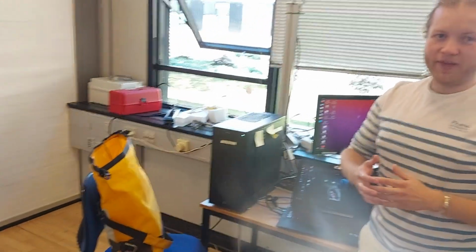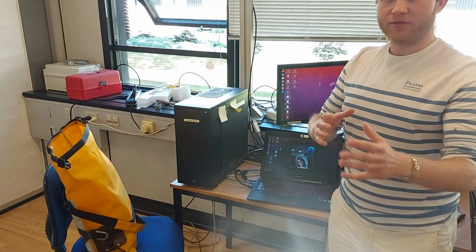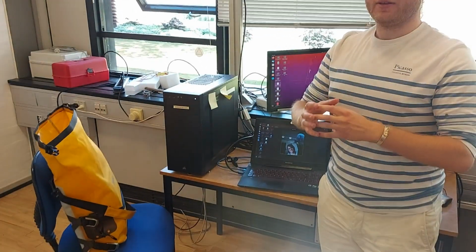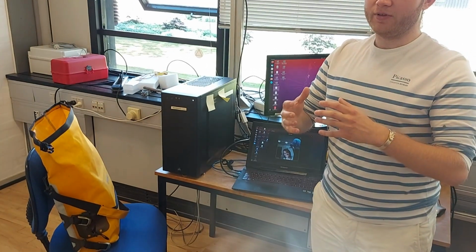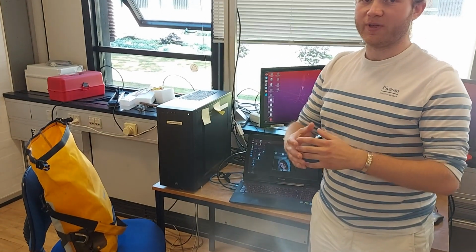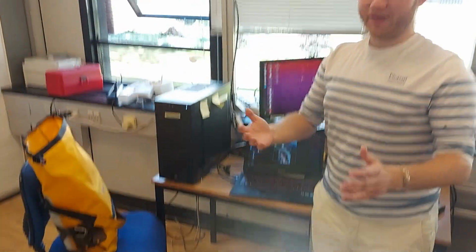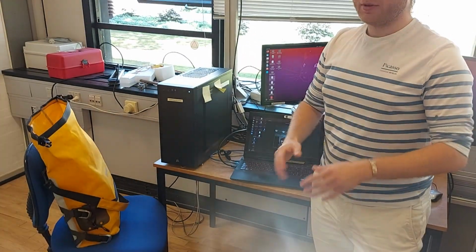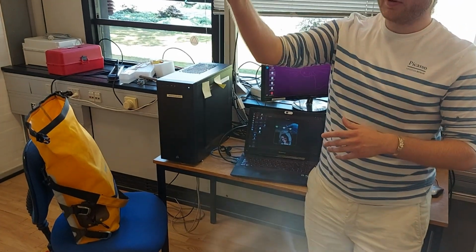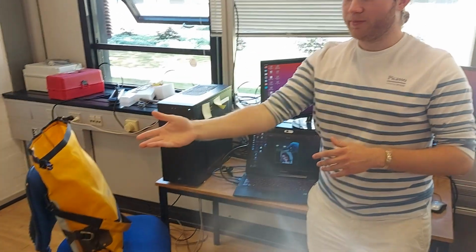Then afterwards, because AprilTag knows the size of the AprilTags that it's expecting to detect, it knows the pose, so position and orientation, of these AprilTags with respect to the base of the camera, because the camera has a calibration file that enables AprilTag to do that conversion. These poses are then converted from the camera base to the robot arm base.